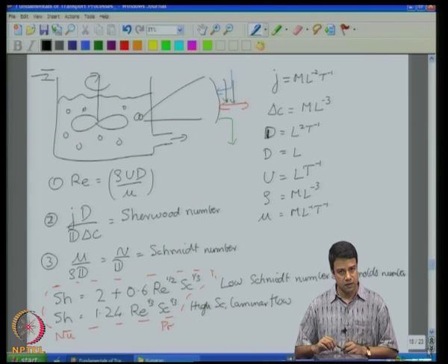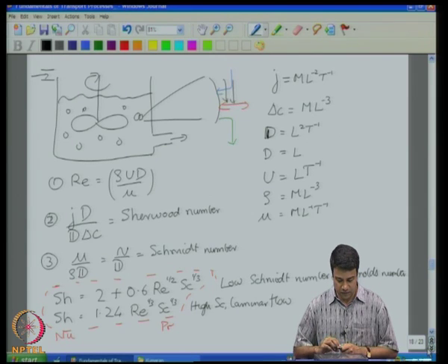And then we looked at the heat transfer and mass transfer from the surface of a catalyst particle. And there I told you the fundamental numbers, the non-dimensional mass flux, a Sherwood number, a ratio of a mechanical quantity, viscosity, and a mass transport quantity, the diffusion coefficient, and the Reynolds number, basically because the fluid flow is what is transporting mass to the surface. And we looked at two different correlations, for laminar flow and for high and low Schmidt numbers.